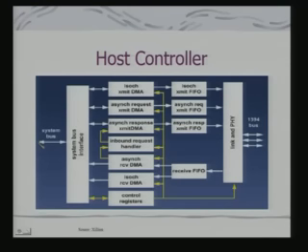And this layer is IEEE 1394, and this is really the interfacing hardware, the physical as well as the link layers of 1394, and typically this is what is to be always powered up, because even when the host, maybe a PC, is not on, the data communication should take place, so these signals should be powered on. And this interfacing is what is interesting and should be noted.